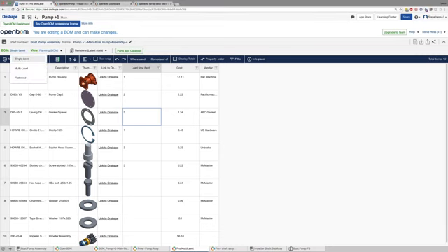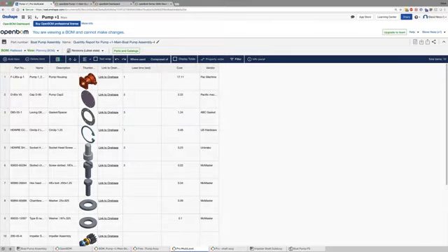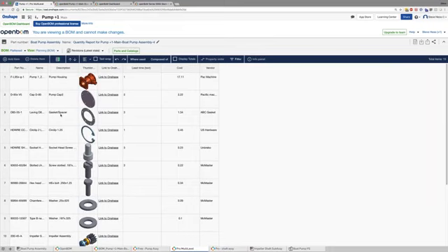Something else I'd like to speak about here is the flattened view. This is essentially what you need to buy and how many of them for the particular assembly that you're looking at. It drills down through the sub-assemblies. If this hex bolt existed in several sub-assemblies at several levels, this would roll it up to a total quantity so that the planning people know what to buy.